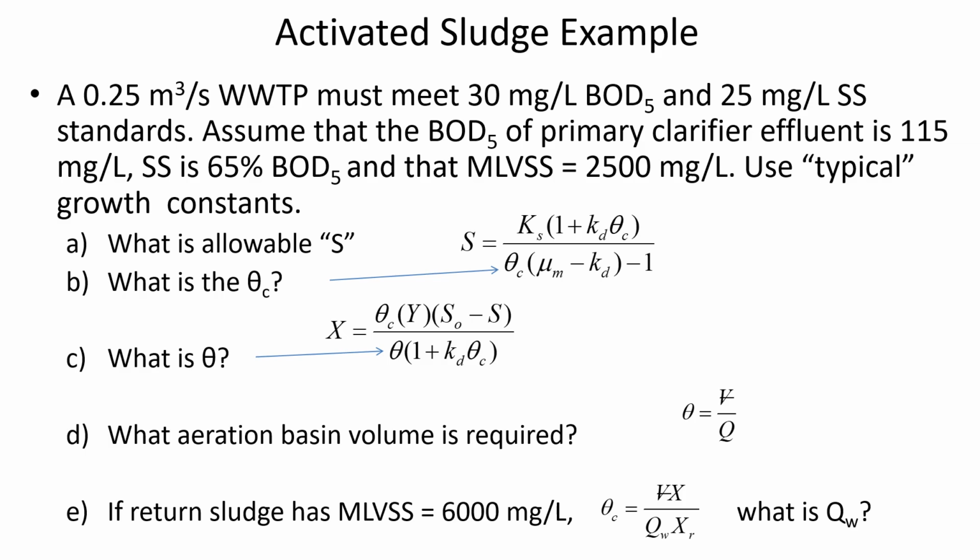So there's dissolved BOD, and a portion of the suspended solids that come out are also BOD. So it's like floating particles of organic material that exert biochemical oxygen demand. So the allowable BOD is going to be reduced because our permit says 30 milligrams per liter are allowed.